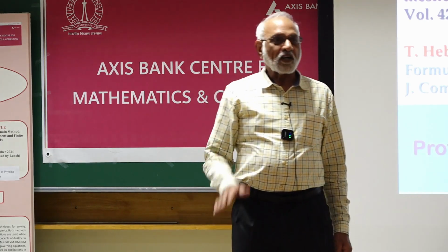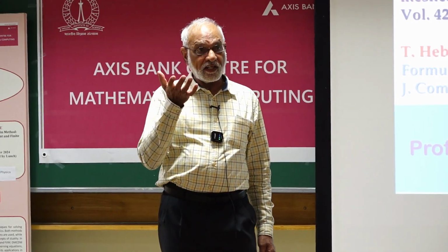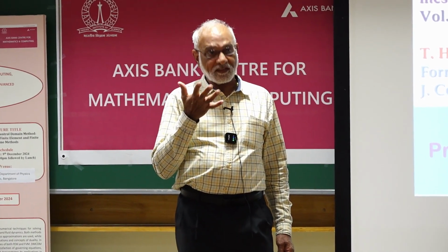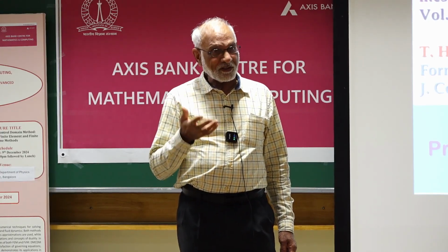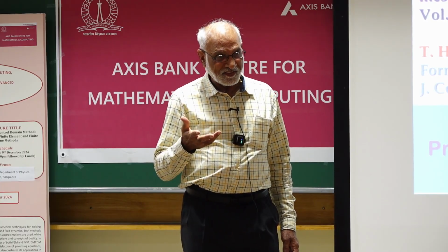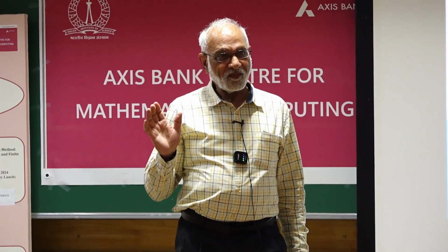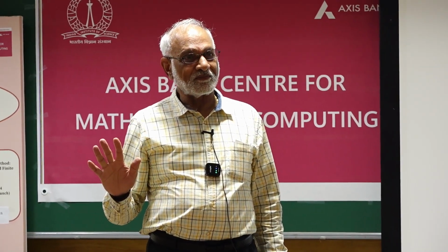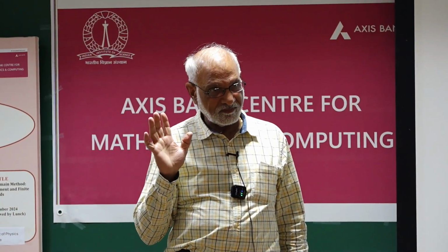So, okay, I think I remember Gopalakrishna, and we talked about it sometimes. All of the higher order theories, including my third order theory, bring higher derivatives, and that requires, in a variationally consistent way, that we also know boundary conditions on higher order derivatives or on their duals. So what we do, conveniently, we put this under the rug, so to speak. We assume the dual variables are zero. Dual variables for the higher order terms, like coupled stress.